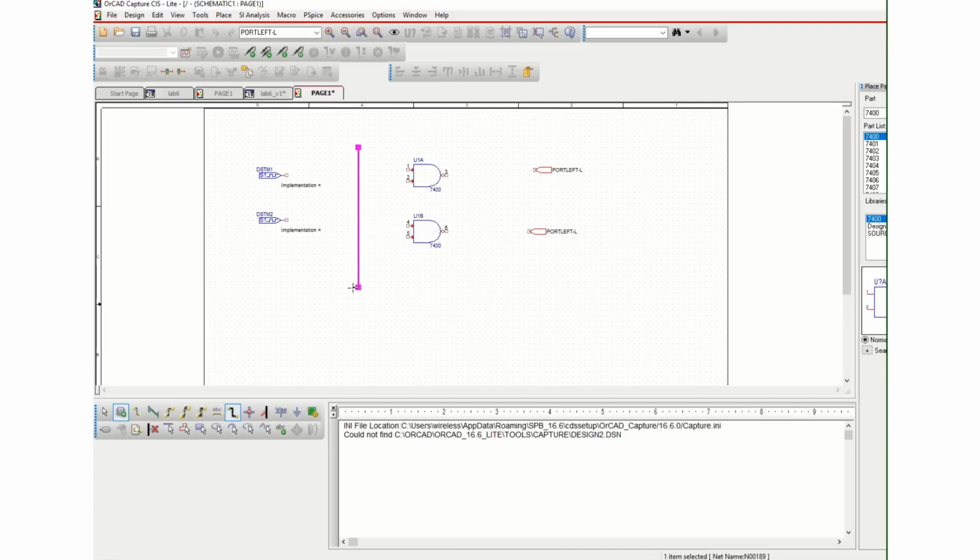If you continue to extend your bus in this fashion to the left or to the right, it doesn't really connect with the original bus like it used to for wires. So the bus implementation is slightly different from wires. You have to have a bus entry placed in between two buses in different directions for the connections in the bus to continue. So there are several ways to connect components onto your bus.